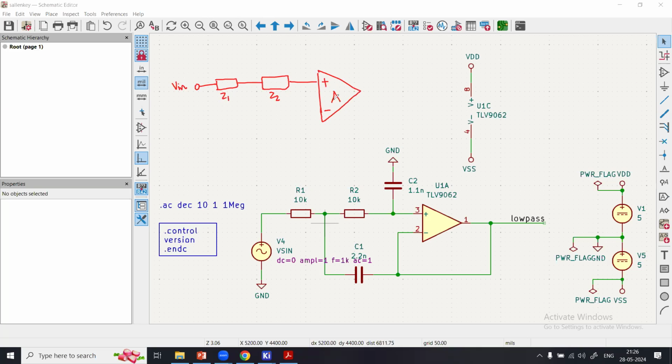Then I have this particular combination, that is an amplifier with a very high open loop gain. The output is specified here, and the negative pin of the amplifier is tied to the output. So obviously this is my buffer, or a voltage follower, a non-inverting amplifier configured as a voltage follower circuit, right? What is the advantage of this?